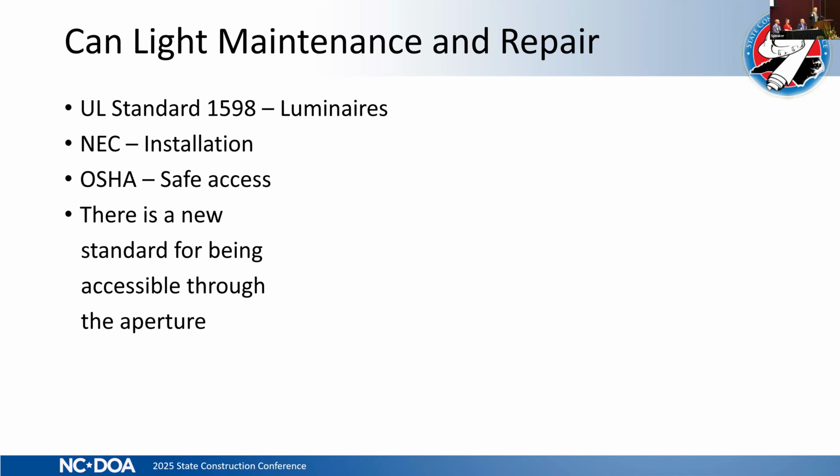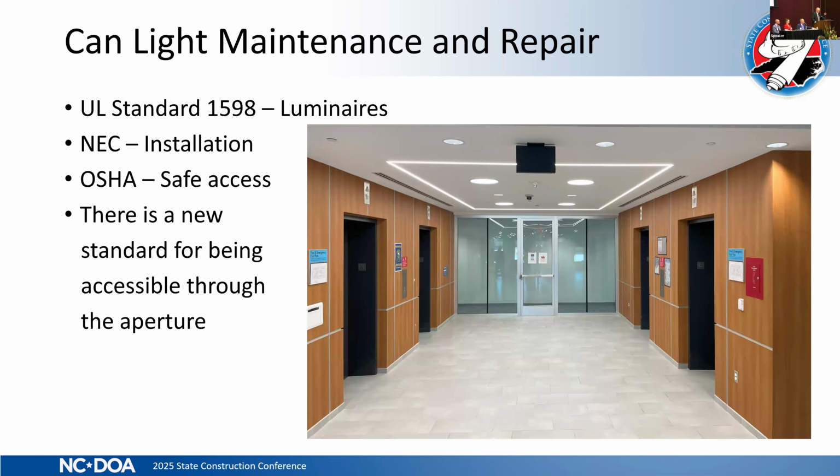So what it allowed us to do was we compared. Do I put in a 2x2 door next to every fixture, and I have 80 of them? Or it turns out these big 14-inch fixtures produce way more light. So we're taking out 12 fixtures and replacing with 4. And I don't have to put any doors. It actually ends up working, and it looks like this. And this is a mock-up before we took out all of the 4-inch cans, or the 6-inch cans.